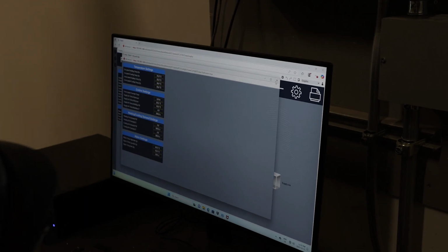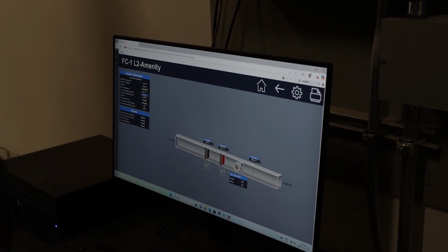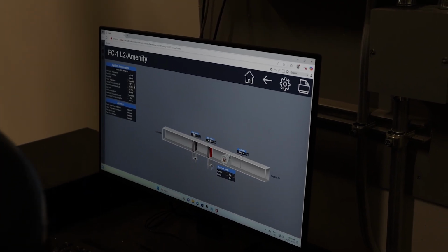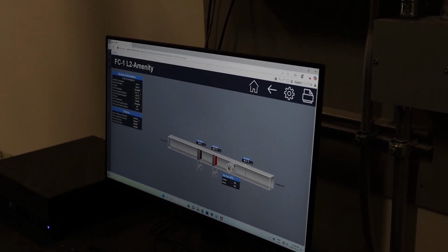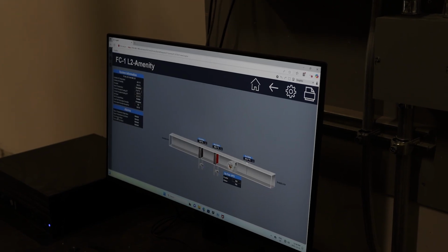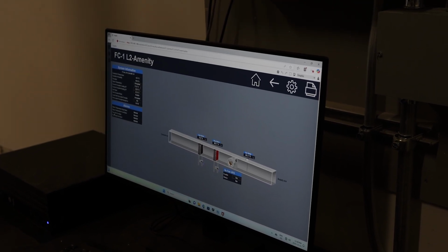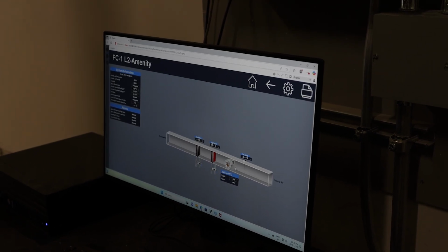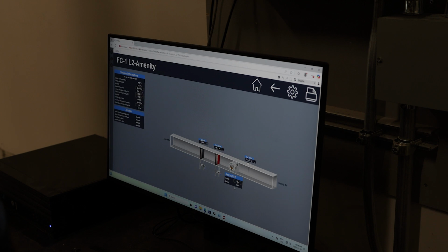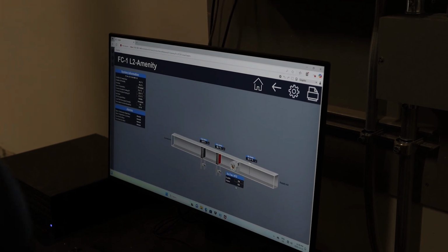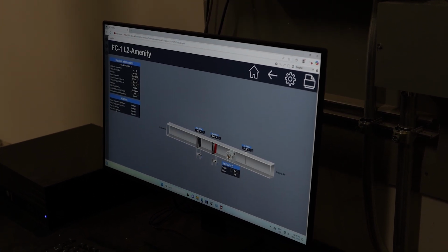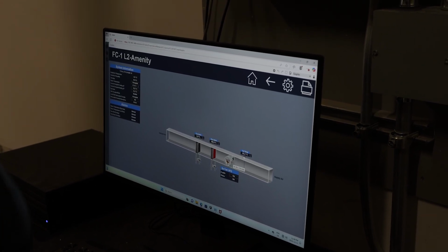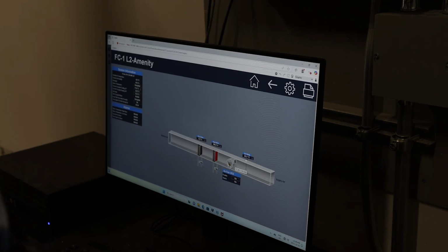For all the DDC fan coil units, they all have a thermostat. If you lock the thermostat, the only way to adjust the set point is from the BMS. We also have alarms for space high temperature and space low temperature, a fan not on alarm, and a fan hand alarm. Fan not on alarm means the command is on but the status is off. We try to run the fan, but the fan is not running. Fan hand on alarm is when you want to turn off the fan, but the fan is still running, so someone put it in hand mode.